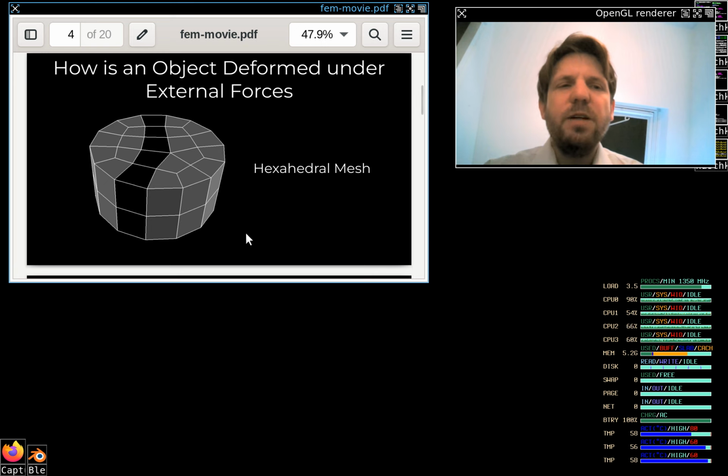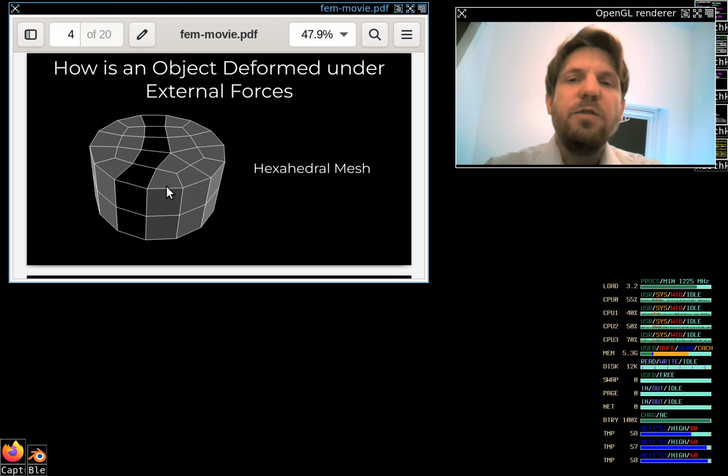This is all about finite elements. And the story here is, of course, the smaller your pieces are, the more you will calculate, and probably the more accurate your simulation will be, if you don't get into numerical difficulties because your objects are too small or you run out of memory. These are things that you want to take into consideration, and of course also how much compute time you have available.